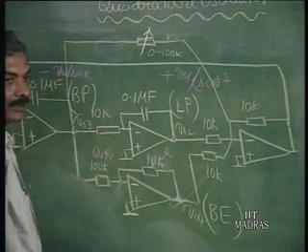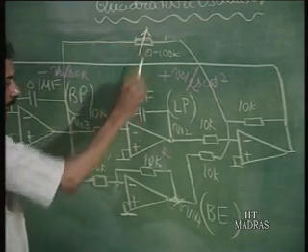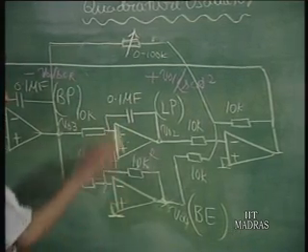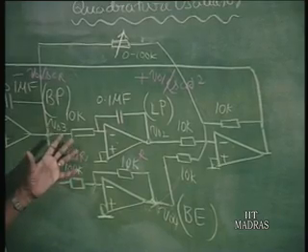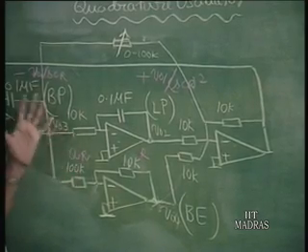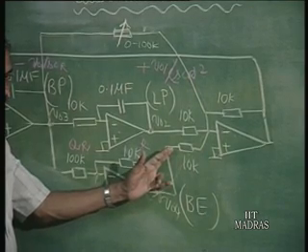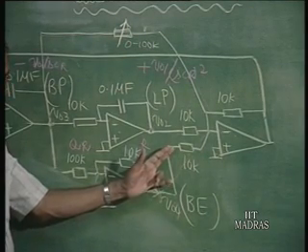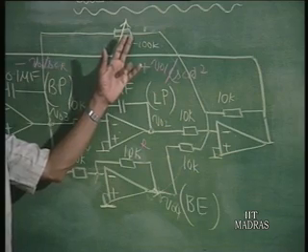That means it is going to introduce positive feedback. So, if I put a resistance around 100K, it should be capable of changing the Q to infinity, because there is a positive Q of 10. This will introduce positive feedback such that the Q can be made equal to infinity.